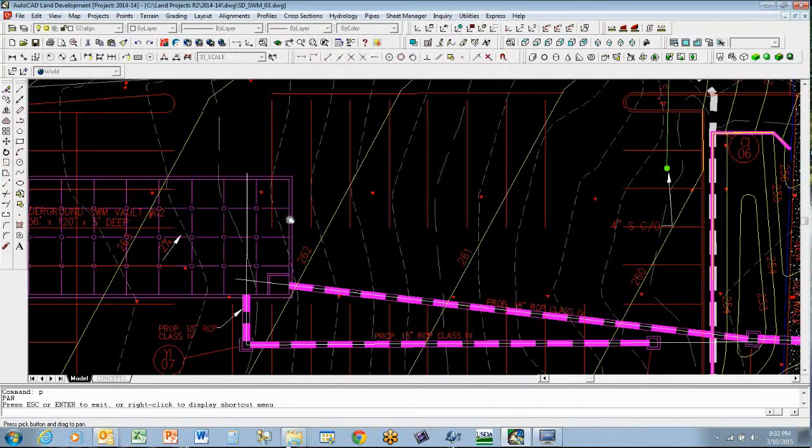One of the things I find helpful is to take an engineer scale and try to find out what vertical scale will be most useful, one that will not take up so much of my paper but will still give enough vertical exaggeration that we can actually see the change in grade, the change in slope, and understand what direction the pipe is flowing.